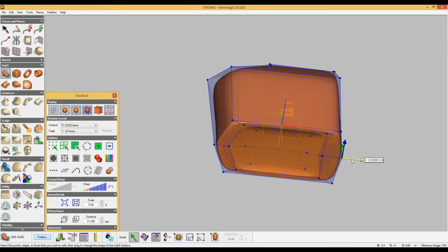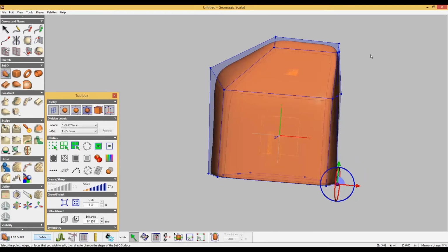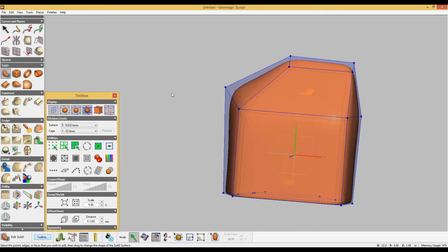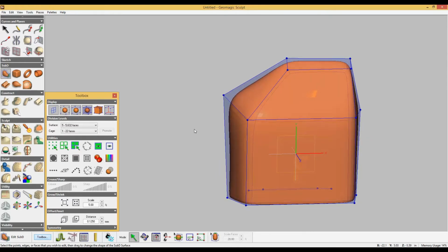Extend the contour of the back for a more rounded shape. Choose the Select tool and click and drag the center points out. Use Add Loop to create another control loop surrounding the top.